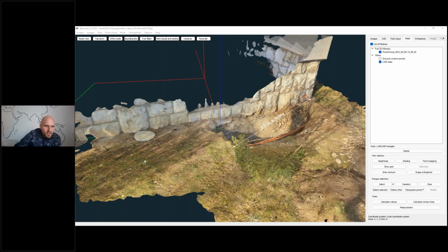Mr. Sefi is asking, what is the success rate of videogrammetry in large areas? Well, for very large areas, I would recommend using drone photogrammetry instead, because if we fly, for example, from 80 meters high, we get images that are approximately 80 meters big. And if by large areas you mean maybe more than 200 meters, even drone photogrammetry will work very nicely. With videogrammetry, it will also work, but you will have to walk up and down the area.